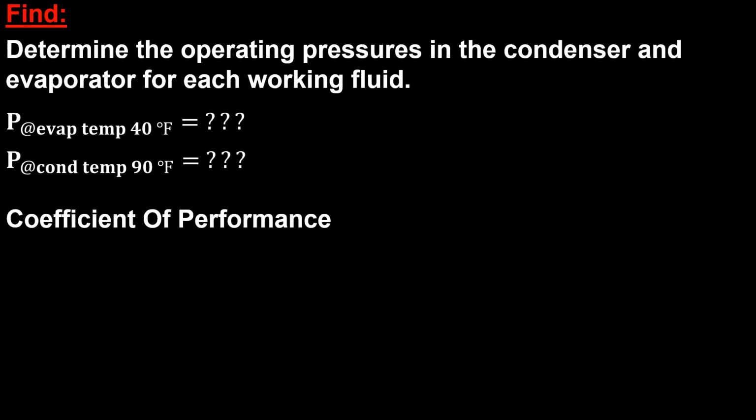And the second thing is we want to find the coefficient of performance, or we call it the Carnot cycle coefficient of performance. So this COP is the maximum theoretical coefficient of performance of any refrigeration cycle operating between the two regions T sub C and T sub H.